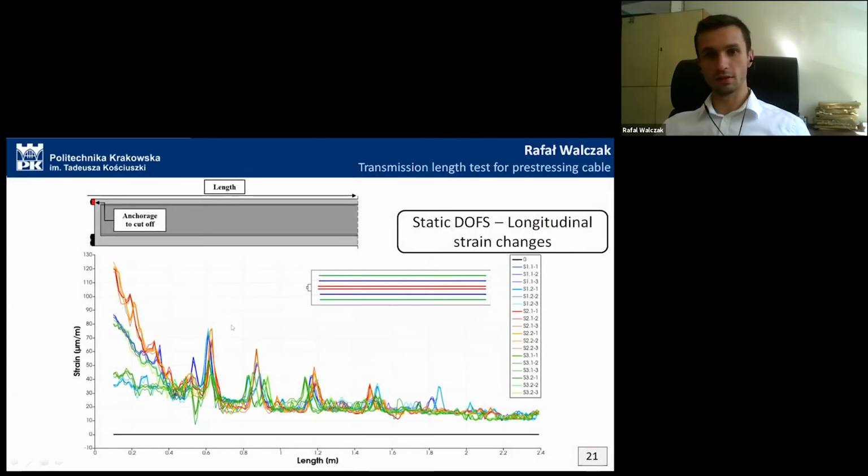Yeah, so the local peaks we can see here, we don't have 100% certainty, but we think those are cracks which occurred at the very early stage of the concrete's life, almost 50 years from now. And their width is just increasing due to the loss of the prestressing force. Actually, we have a new microscope in the lab, so I will try to explore this crack. We also think that it could be cracks because the stirrups were at this spacing, so it's highly probable in our opinion.